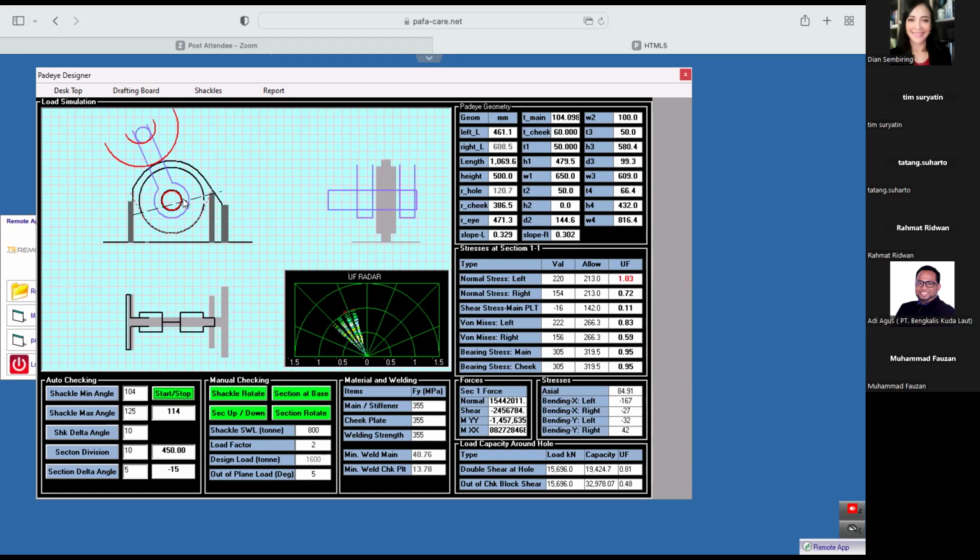Yeah, so it goes here. So basically, here you can see that the extreme stresses or the maximum stresses is not necessarily at the bottom here, but maybe somewhere up there. So we have to be careful that, okay, this one is not included, these two are not included in this section. So we might need to change the design of the bed eye, or thicken the shape, or thicken the main plate maybe.